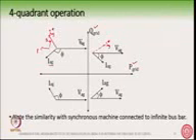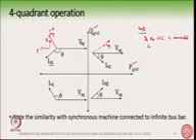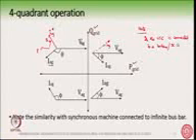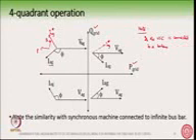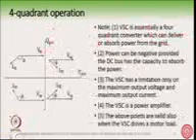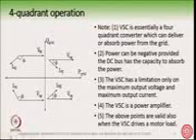Now, this phasor diagram can only be drawn, remember, and there is a note here that we will explain, that this is only possible if the VSC is connected to a battery or something like a DC source which can absorb power. It can give power as well as absorb power. Okay, we will explain this. So this is the phasor diagram which is possible. This is what I wanted to convey here.